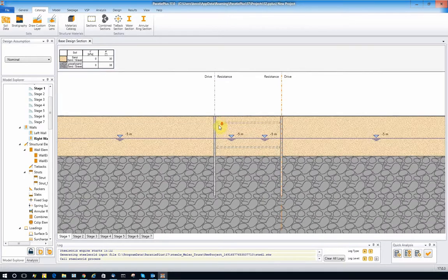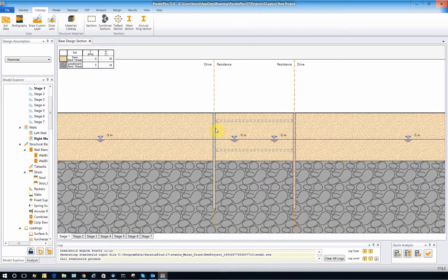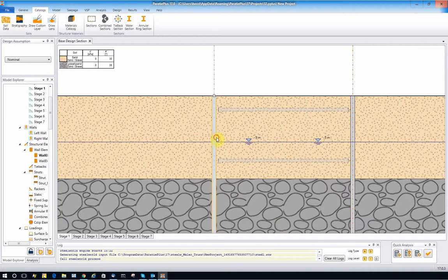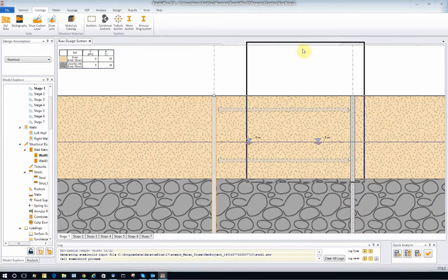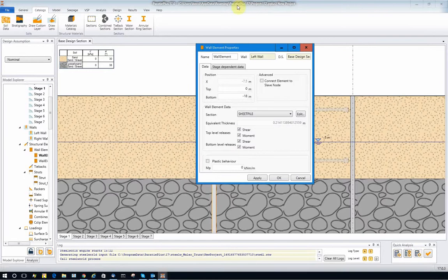Now we define the retaining walls at each part. In this case, due to the symmetry, we will consider the same shape for all the parts, but we can also provide different shapes for the retaining wall on the opposite walls. Let's see what we did in this case. In this case, we consider the sheet pile down to elevation minus 18.